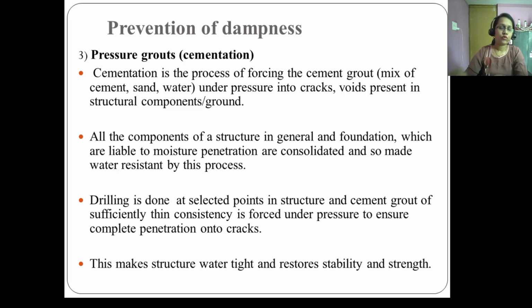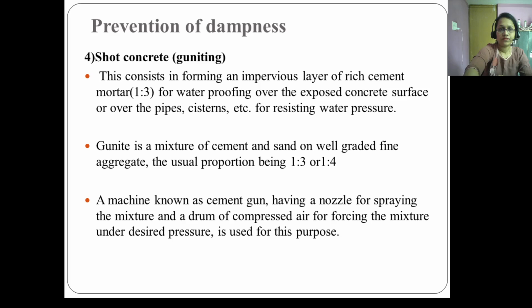All the components of a structure in general, and the foundations which are liable to moisture penetration, are consolidated and made water resistant by this process. Drilling is done at selected points in the structure, and cement grout of sufficiently thin consistency is forced under pressure to ensure complete penetration into the cracks. This makes the structure watertight and restores its stability and strength.